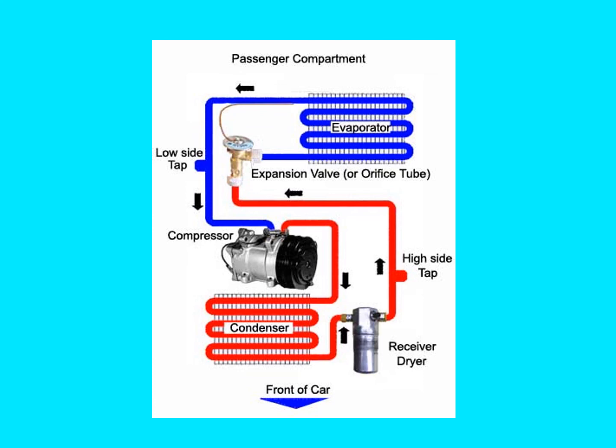So from there, the refrigerant flows into the receiver dryer. From the receiver dryer, it's going to flow as a liquid up to the expansion valve. There, on the other side of the expansion valve, we can see things are shown in blue. That's low pressure. Okay, so the refrigerant goes through the expansion valve, and on the other side it's low pressure. It goes in as a liquid. So we have liquid, low pressure refrigerant going into the evaporator.